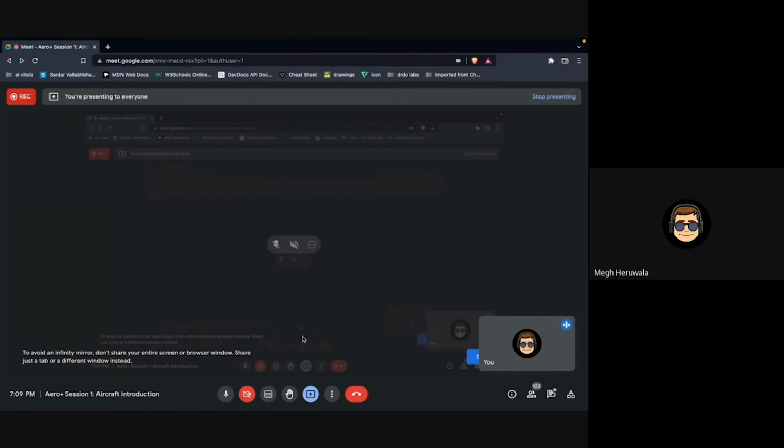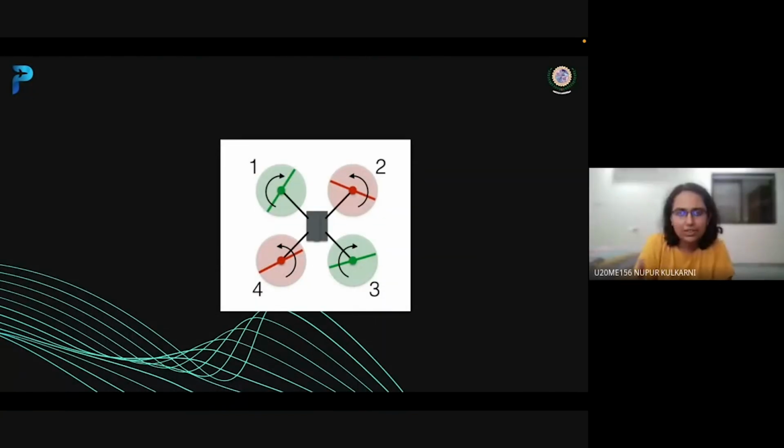Okay. So in a tricopter, there are 2 ways to avoid this. The first way is we can increase the propeller size of one motor and compensate that torque by the other 2 rotors, or we can add a servo that can rotate one arm or 2 arms of the tricopter and balance the torque. So it's more complex, but yeah, good question. A similar mechanism is seen in tricopters also, but it is somewhat difficult to analyze. So for now, that is the basic concept.